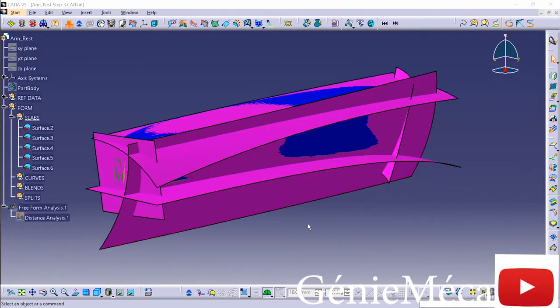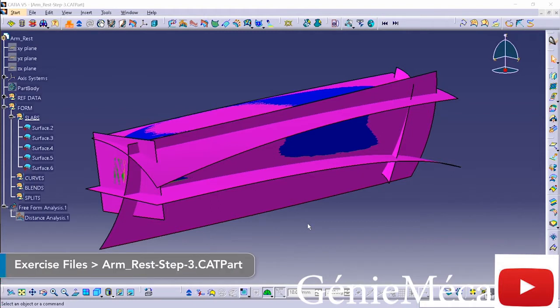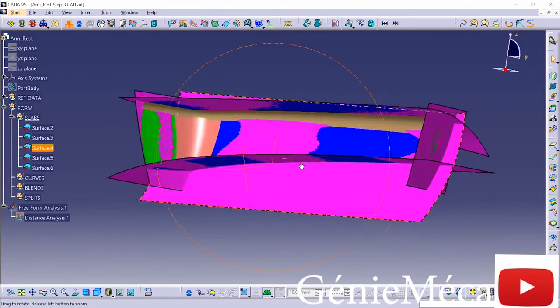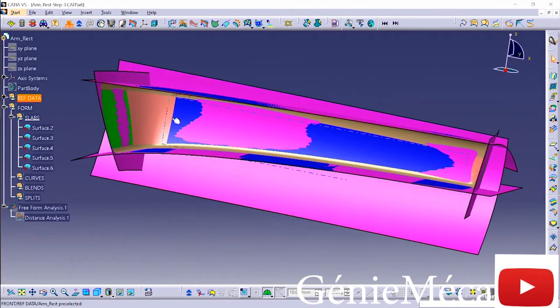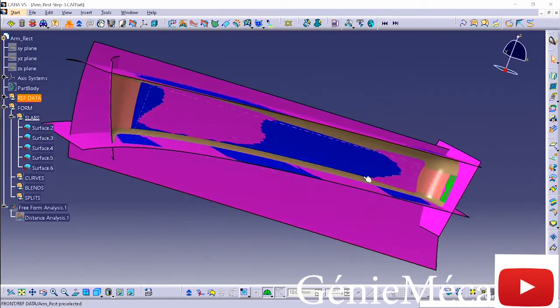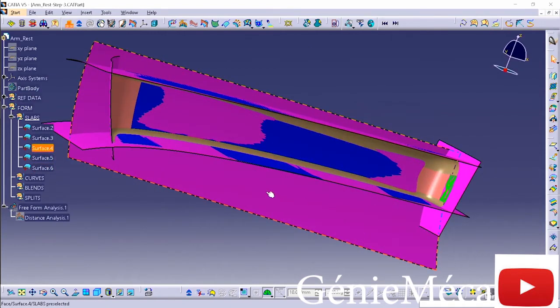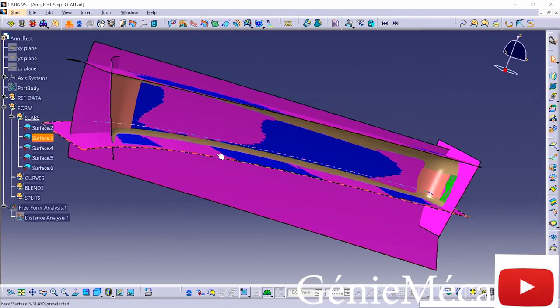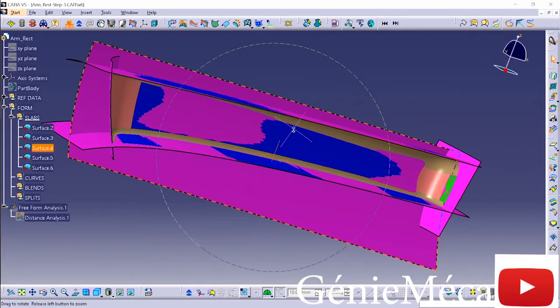Now that we have our primary surfaces set up, the next step is to create our secondary surfaces. So we're going to take a look at the mesh and figure out the next logical step is going to be these blends on either end, the large blends. These bottom blends that wrap around are going to be constructed afterward. So we need these secondaries here in order to build these additional blends across the top and the bottom.